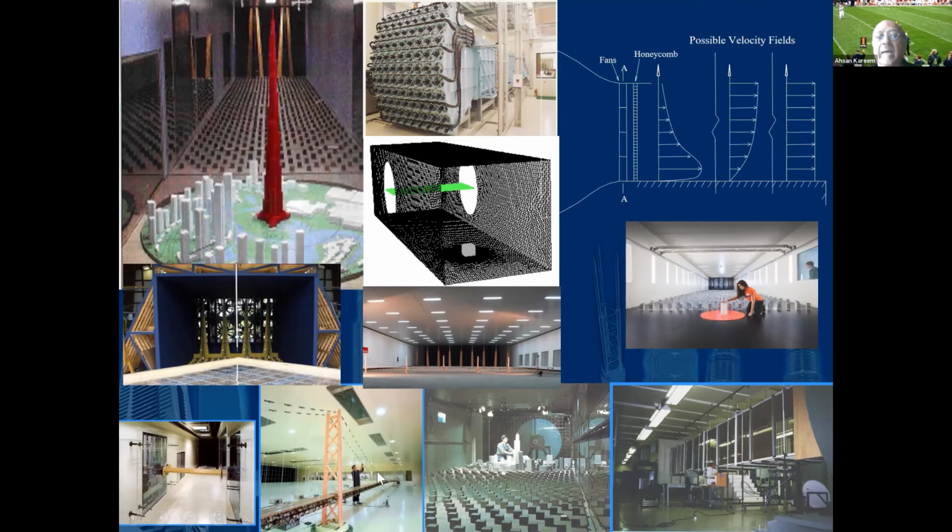It is in Tsukuba, which was built for the Akashi-Kaikyo bridge, where you could put 2 tennis courts inside that building, that wind tunnel. Then we have certain wind tunnels where we look at the cross-sectional property of the bridges, or for others, long towers, and then use mathematics to expand that for the overall modal analysis. Now, there's another type of wind tunnel coming up with a lot of multiple fans. It started in Japan, and now it is going everywhere. I think there are 7, 8 of those available at this time.